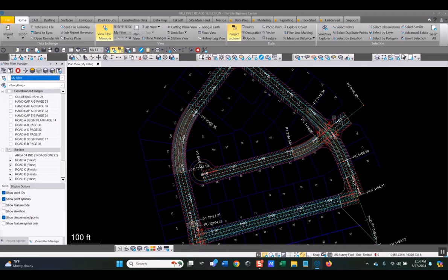You can also, again, I'm going to show you one more time. Several people don't know that if you picked or selected the wrong thing, dadgummit, I didn't want this line. Well, as long as you have the control key down, you pick the highlighted entity and it will unhighlight or remove those entities from the selection group. All right, great. So that's singular or individual entities.